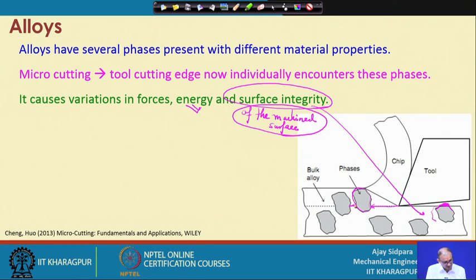Now, let us consider this is the grain. It is exactly the opposite: only a small portion is located inside the machining zone, but most of it is within the uncut chip thickness. So, when the tool encounters this, the whole grain will go out, and instead of a flat surface you end up with a scoop or cavity. So, this is what is happening in this case.